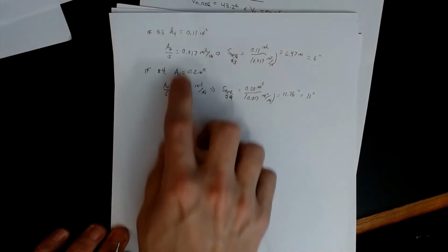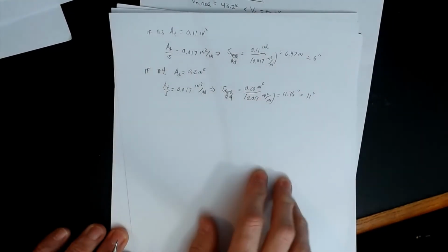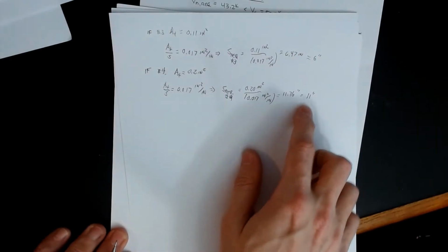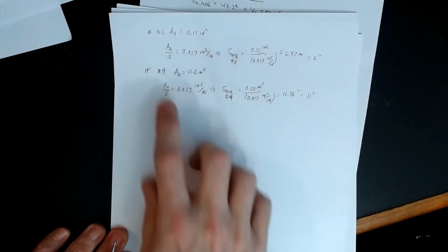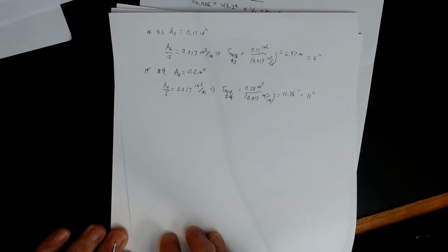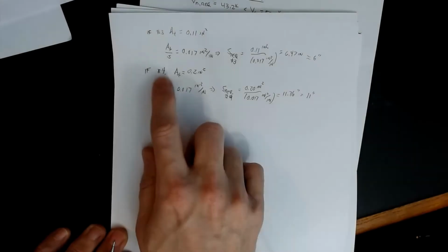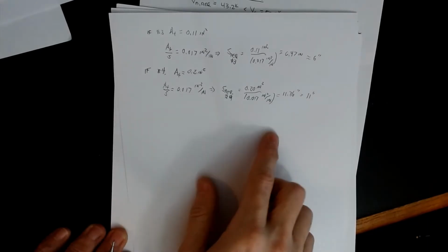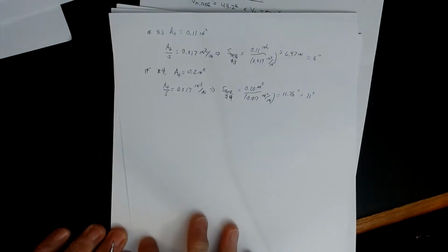So you can see a big difference in the size of the bars, what they do on the spacings, right? Basically you cut the number of bars you need in half by going to a number 4. And that's a pretty standard stirrup size for a lot of beams, a number 4. It's kind of optimal. Okay, so what do we do with this value now that we've got it?